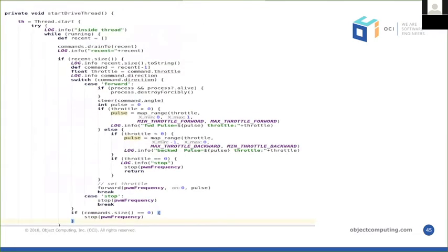All right, so here's a drive thread that's running, and what we're doing is we're trying to create a queue and figure out whether we're going forwards or backwards or stopped in the car itself. When you're using that joystick to move around, it's going to give those values of a gradient between +1 and -1. -1 being full speed backwards, +1 being full speed forwards, 0 being stopped. So we just try to figure that out here and recreate the thread if it crashed for some reason.